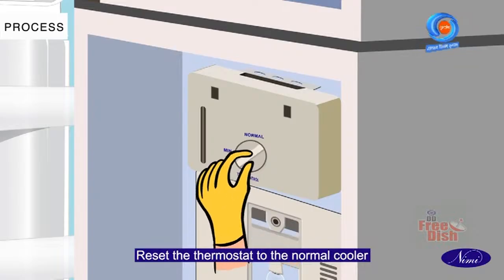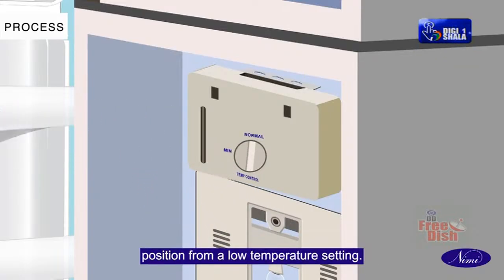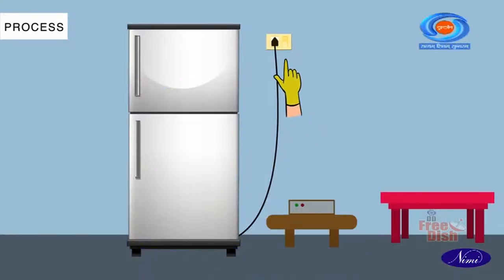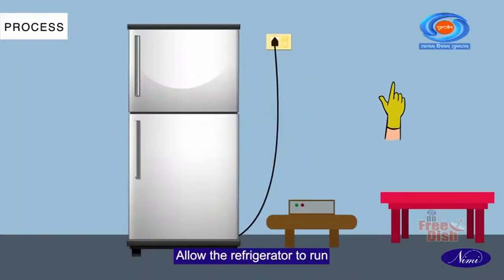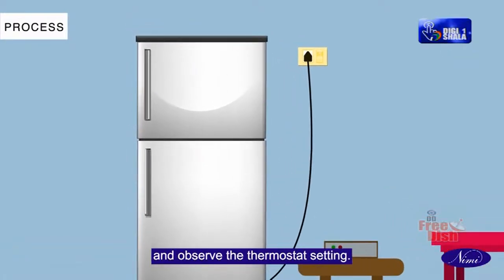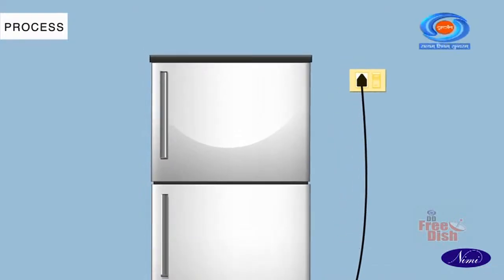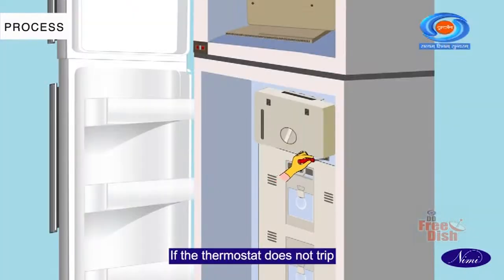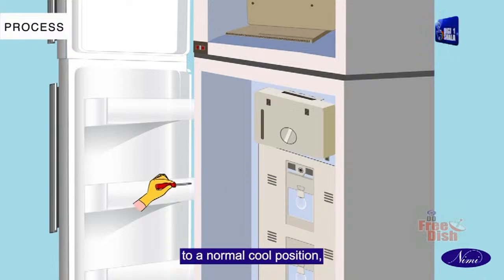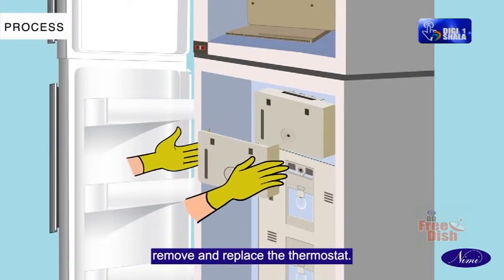Reset the thermostat to the normal cooler position from a low temperature setting. Allow the refrigerator to run and observe the thermostat setting. It should trip to a normal cool position. If the thermostat does not trip to a normal cool position, remove and replace the thermostat.